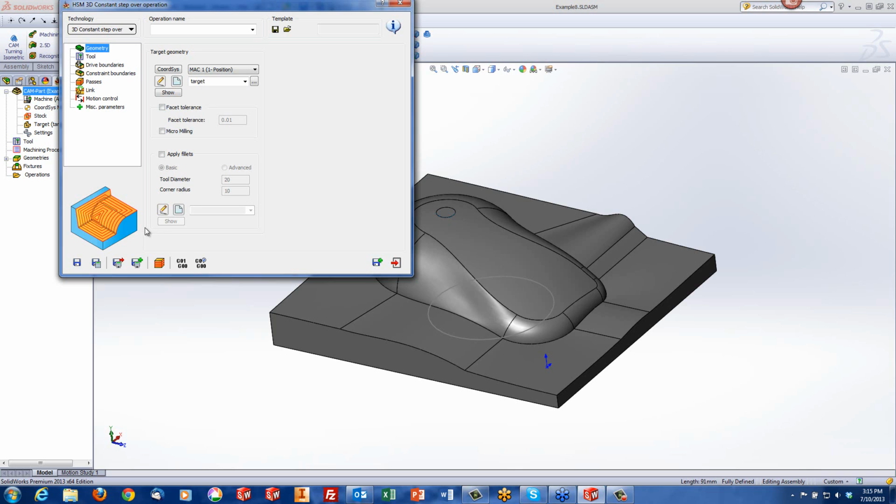if you're working on a surface that has a curve on it, such as this one over here, when you tell it to move over every millimeter, from the top view it looks even, but as it goes down on the surface, since it's a 3D surface, it works itself further away each time. In other words, the step on the part itself is further and further away from each other, so you're not going to get a really nice cut.